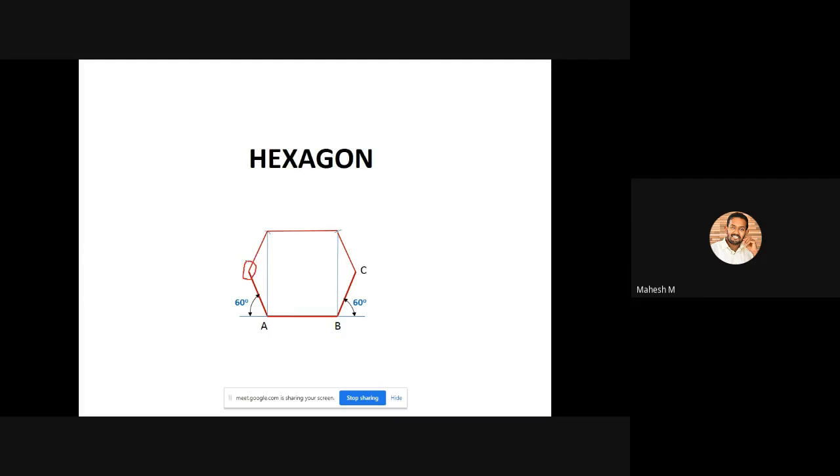If you want to create a side hexagon, you should draw a vertical line first. After that, you should create an inclined line with an angle of 60 degrees like this. Then you can project 2 horizontal lines from the 2 points. Then you'll be getting another 2 corners. You can connect these 2 corners with the previous points. So finally you will get the side hexagon.